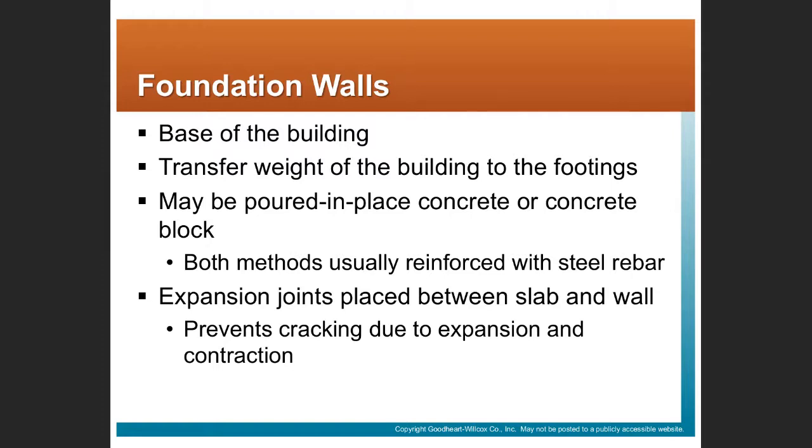You've obviously seen them your whole life. You may not have thought about why they're there, but they're there for the same reason, right? They're giving that concrete at the surface of the sidewalk some place to go when it expands due to an increase in temperature.